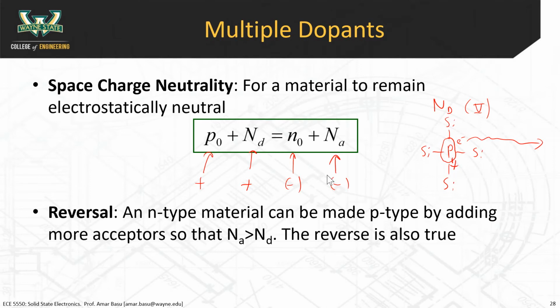So a typical practical problem that I would give you is that you dope the semiconductor with a doping density of X. Your Na is equal to this many dopants per cubic centimeter. The donor density is this many dopants per cubic centimeter. What is the electron and hole concentration? That's what your module 3 homeworks are going to be all about. Draw the Fermi diagram to find the concentrations of electrons and holes. If I give you Nd and Na, that's not enough to solve for P0 and N0. You actually need some more information, which we'll now talk about.